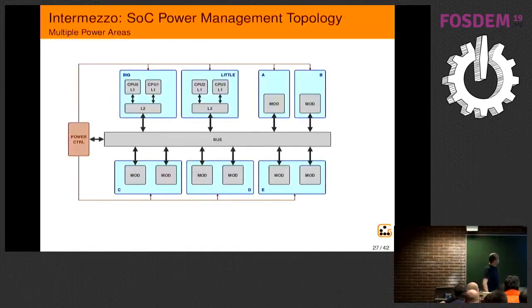So how do SoCs do power management? Typically you have lots of devices, and they're all controlled by a power controller. The power controller can turn off power to one device when it's not in use to save power. Usually in embedded, people care about power consumption. In server space, they also care, but less. Of course, you cannot use a device when the power is turned off.